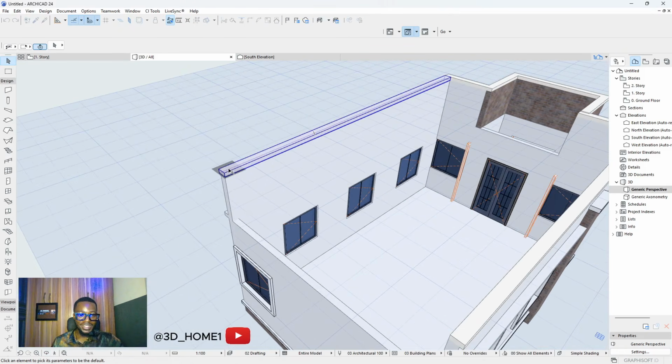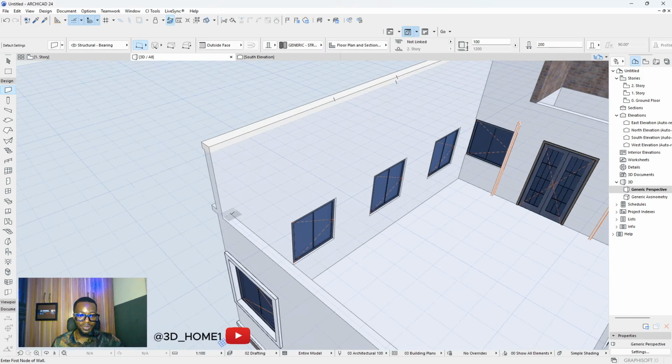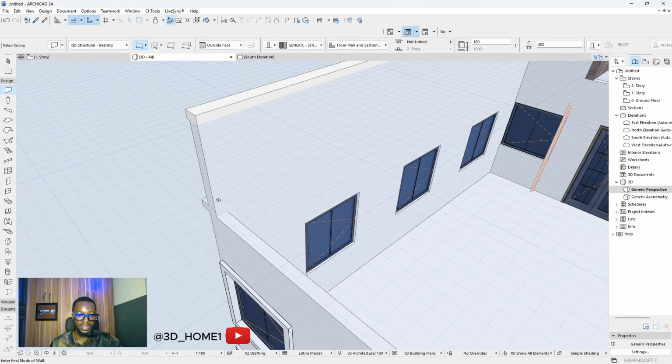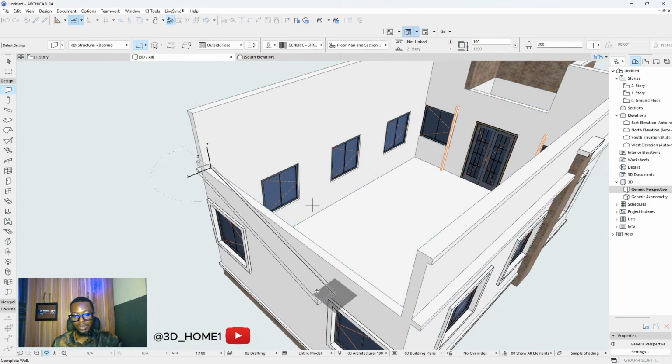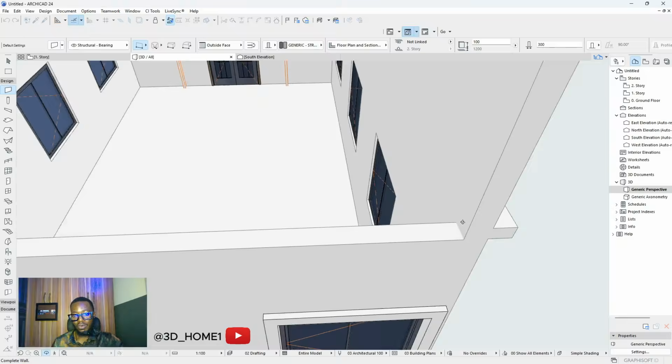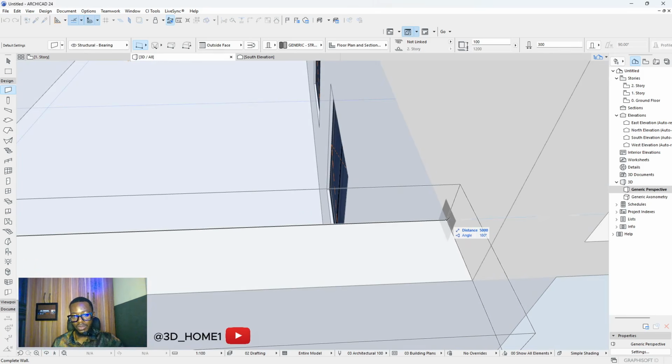Pick up parameter, select this. Okay, pick from, but instead of one leaving on 200, let's say 300. So we'll click from here, bring it all the way out. Press Ctrl, turn O to orbit. Press O again to remove it.